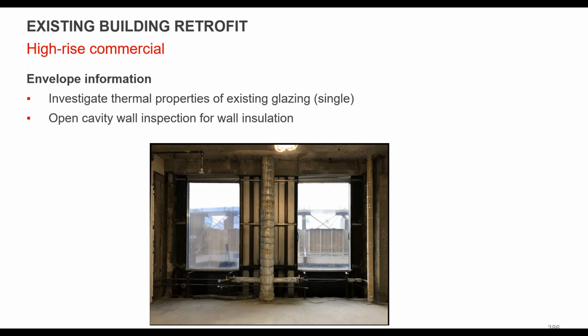They had a couple broken pieces of glass, so we were able to get those tested to get the performance of the single pane glazing that was in there with steel frames. But this gave a really good idea of what the existing condition was, right? You don't get this very often, but in this case, we see that there's basically uninsulated cavity, single pane windows,